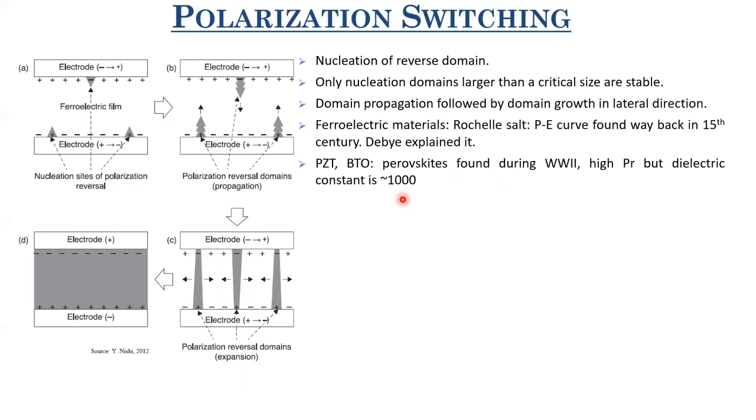Won't your gate capacitance increase significantly? And the moment your gate capacitance increases, the speed with which you can operate with that kind of capacitor also reduces. Anyways, think about this once. And also these materials are not CMOS compatible. So none of the CMOS industries would actually like to go ahead with these kind of ferroelectric materials.